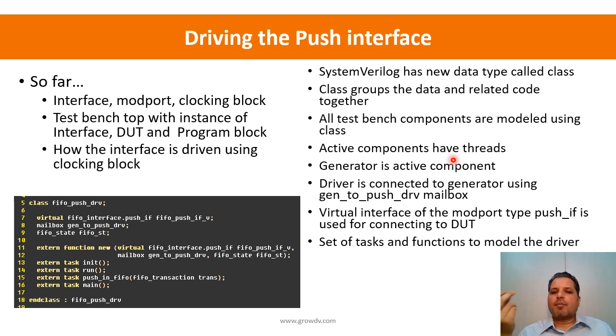If you remember, we looked at the FIFO transaction. We will look into it in more detail further. The FIFO transaction is a class instance that gets created again and again. If you want to issue 20 FIFO operations, then 20 times a FIFO transaction gets created, and as soon as it is driven out or as soon as we have received a pop, it gets destroyed.